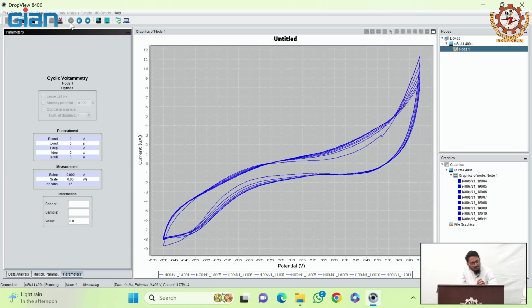So after the functionalization, or the electropolymerization, is completed, we will proceed with the stabilization step, and once the stabilization is done, during the calibration we will be using the counter electrode that is located on the PCB. So if you remember, until now we are using the platinum based external counter electrode, but once our functionalization step is over, we will be using the PCB based counter electrode.